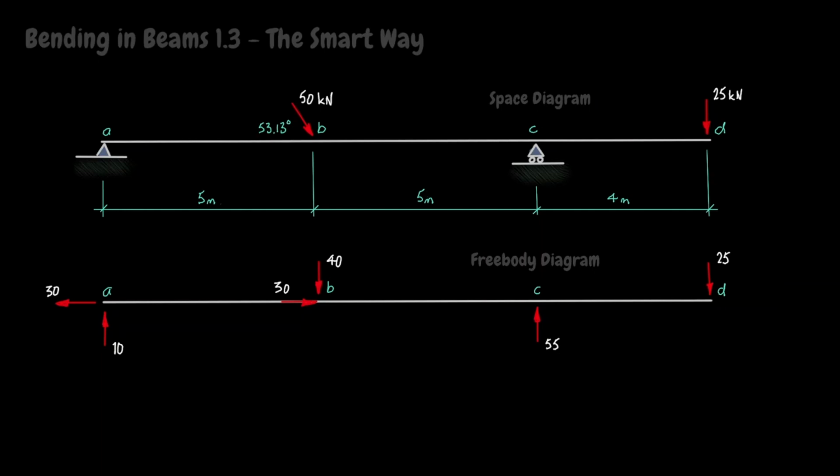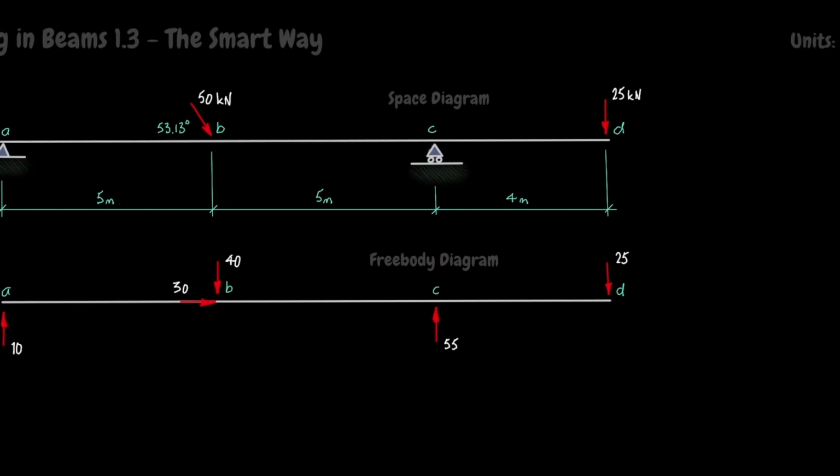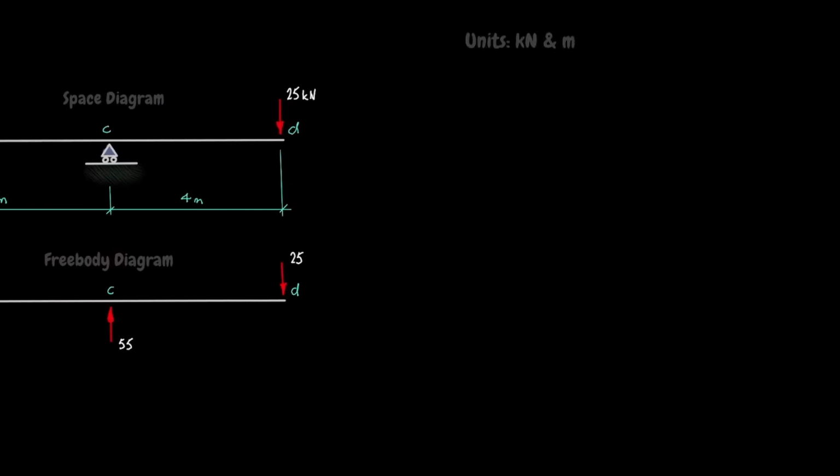This video takes things up a level by presenting a quick, easy and foolproof way to go about drawing axial force, shear force and bending moment diagrams. It's the way a structural analyst would do it. We're dealing with a plane structure, so there will be axial force, shear force and bending moment in the beam. And we're going to need a sign convention.